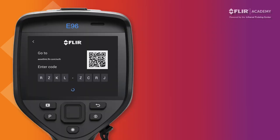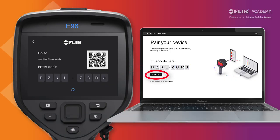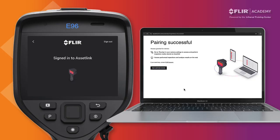Next, open a web browser on your computer and go to assetlink.flir.com/auth to load the Assetlink authorization page. Enter the 8-character pairing code that's displayed on your thermal imager and select Start Pairing to connect the camera. You might be prompted to sign into your Assetlink account to complete the pairing process. If so, this is the same username and password that we mentioned earlier in part 1 of this tutorial when originally setting up an Assetlink account. Once the pairing is complete, both the website and your thermal imager display should update with a confirmation screen indicating the process has been successful.